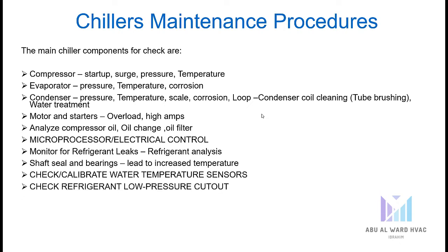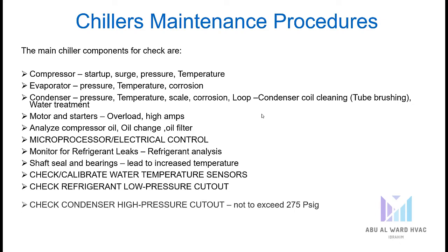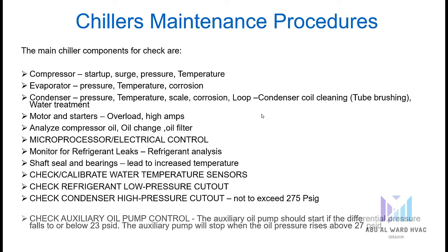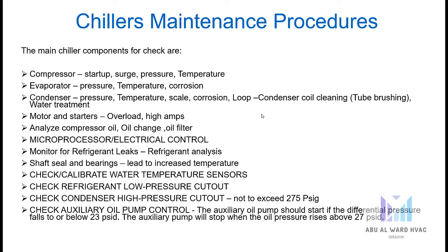We need to check the refrigerant low pressure cutout. We need to check that the condenser high pressure cutout does not exceed 275 psig. We need to check auxiliary oil pump control.